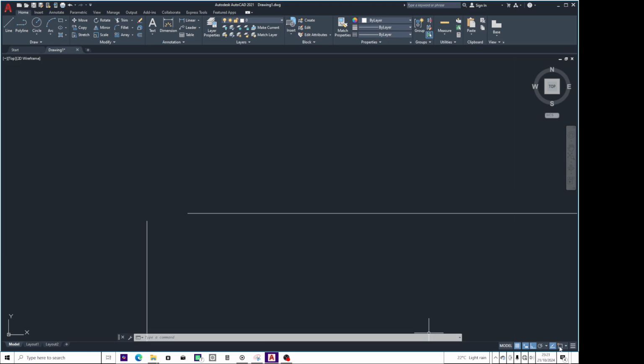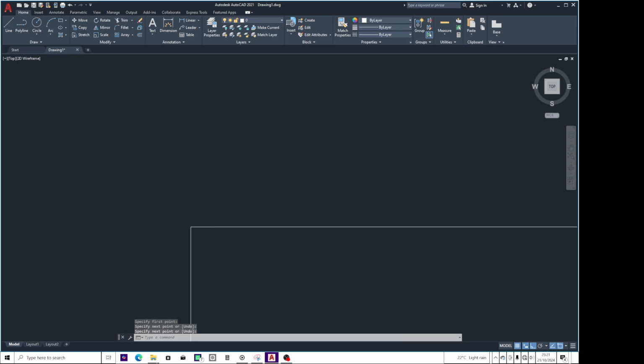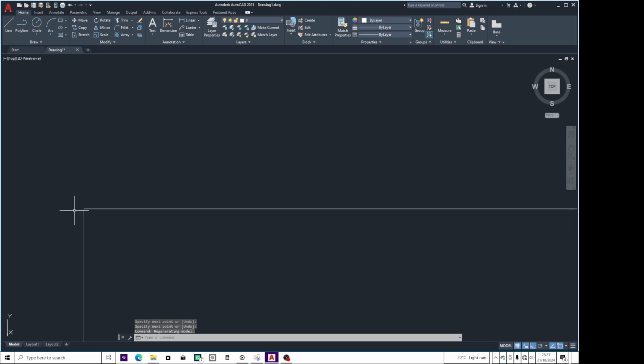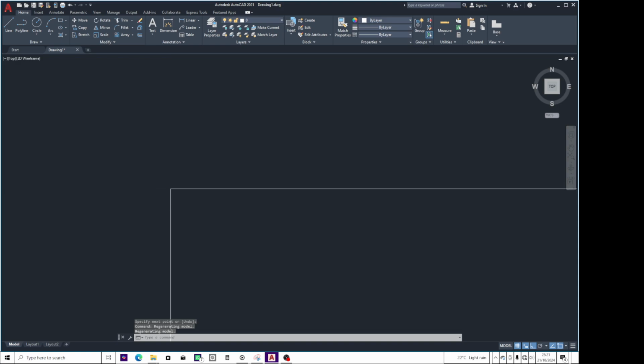So this also gives you accuracy. Activate it, and now once I click my line and I pause over, now I have my line at a point or at the end point. Even if you zoom, you have everything right intact.